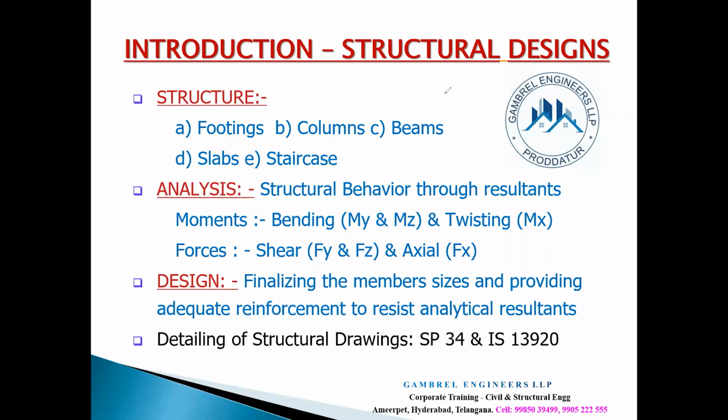That's all. So if you can find bending moments, twisting moments, shear forces and axial forces, depending on the transfer of loads from element to element, slab to beam, beam to column, column to footing, right? Depending on the orientation of the elements and the loads transferred to them, there would be a change in the resultants. A beam will have bending moments and shear force majorly, and not much axial force. It doesn't mean it has zero axial force, though beams have very little axial force, so that amount would not affect our design.